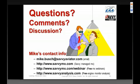Okay, George is wondering, isn't there a risk of leaning to the point of engine cutoff when you briskly lean? No. I suppose it's possible, but I've been doing this for a long time, and it certainly never happened to me. Don't get carried away. But if you pull the red knob back in a fairly brisk fashion, and you stop the moment you start feeling the engine losing power, that's the place you want to start lean of peak, and then you may want to fine tune a little bit from that point. But it will get you safely through the red box, the red fin, or whatever you want to call it, in the minimum length of time.